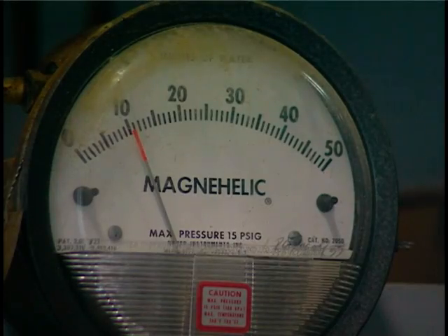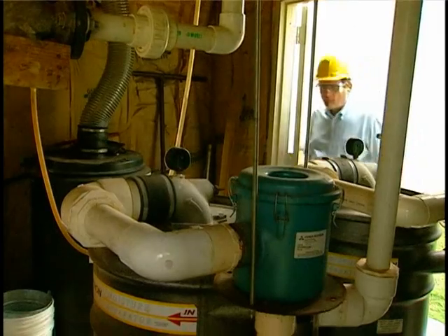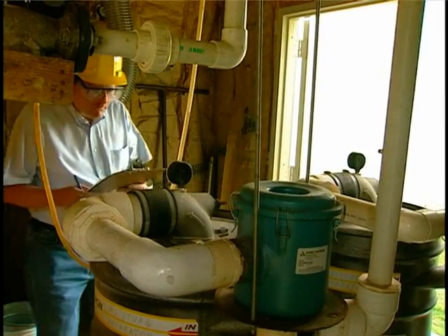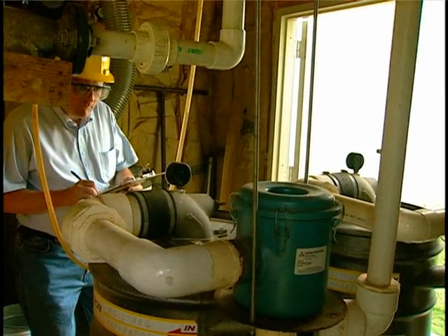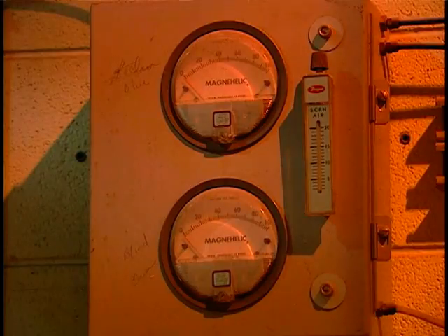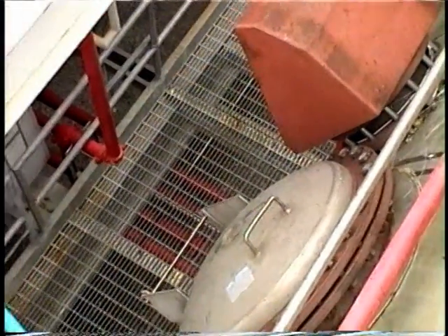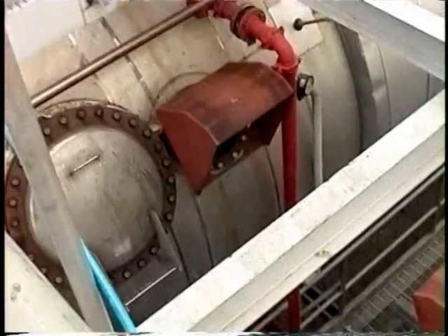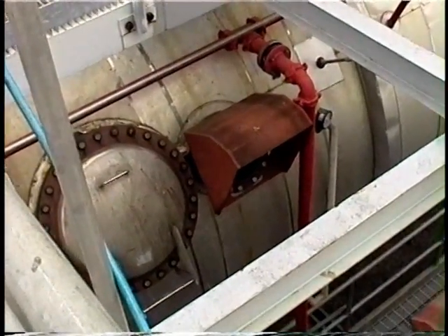An increase in the pressure drop can also be caused by accumulation of particulate matter on the inlet side of the bed. The blinding of some of the carbon granules together with poor gas flow distribution will cause increased emissions. Decreased pressure drop is usually due to partial or complete collapse of the fixed bed because of corrosion of the support grid. This will also cause increased emissions.